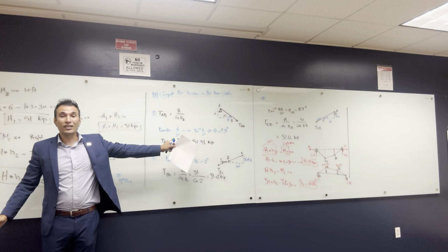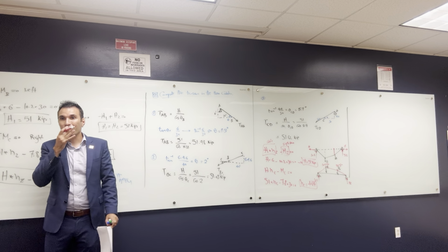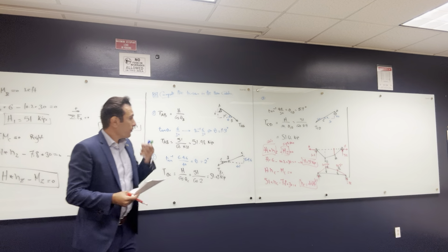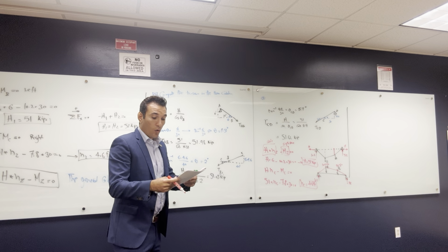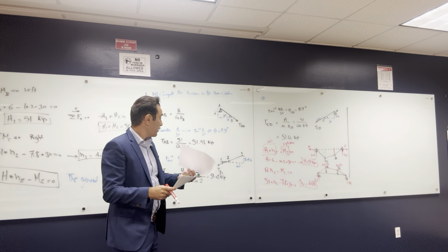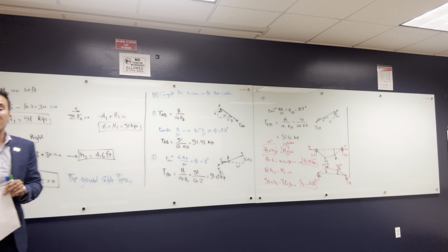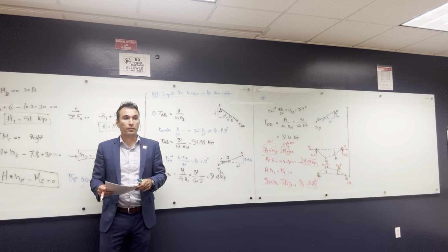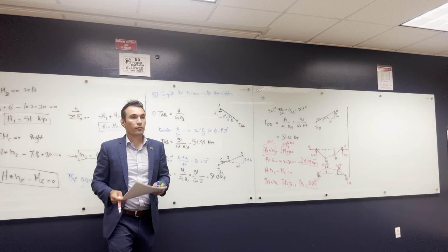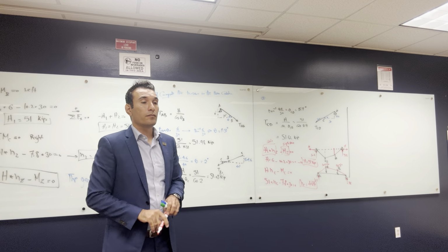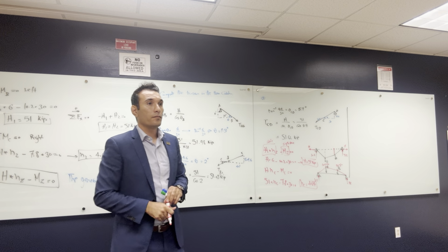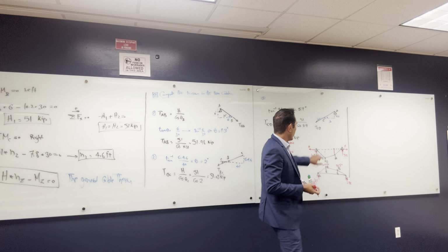So that's what we did here. It's the same thing. All right, so that is called the general cable theory. Use it in the exam, it's going to save you a ton of time. Basically, if we want to do it with the graph, we just put the forces on top of the cable, treat it as a beam, and find the height here at the core.